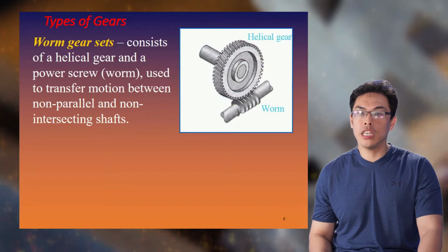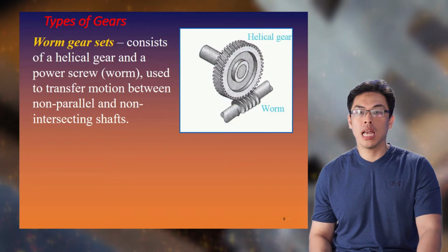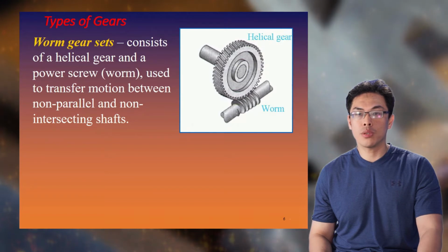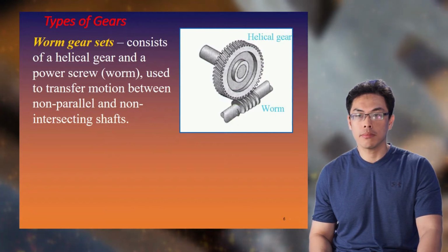Friction is an issue with all worm sets. The worm gear cannot transfer motion back to the worm drive in most instances. Lubrication and the ground teeth both contribute to the set's overall silence while minimizing friction.